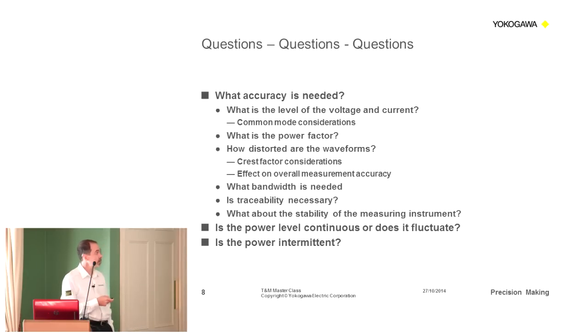What's the power factor? Power factor actually has a big impact on the accuracy of the measurement at the end of the day. How distorted are your waveforms? We've got crest factor considerations. I'll talk about that a little more in due course.